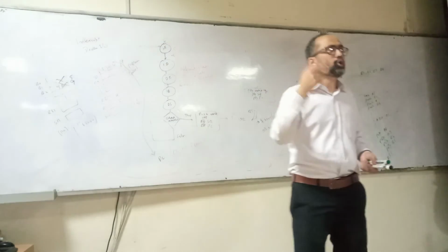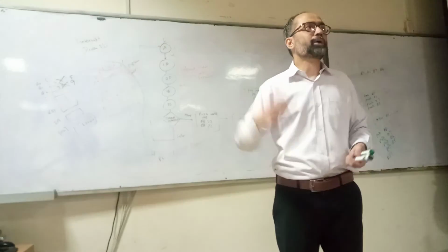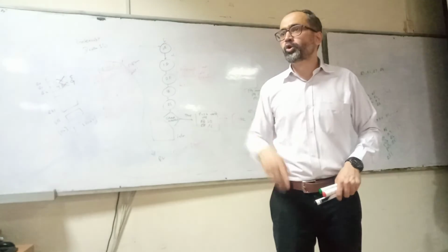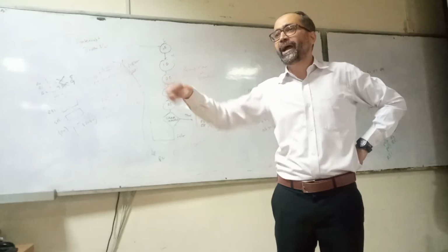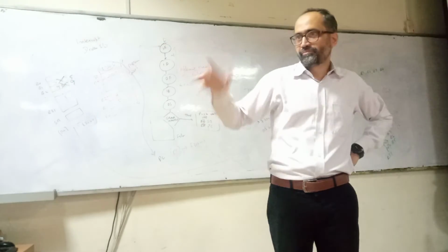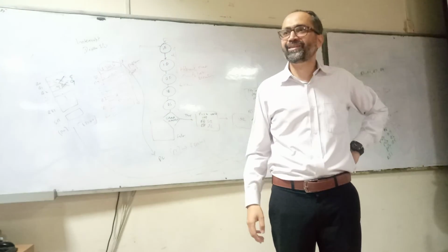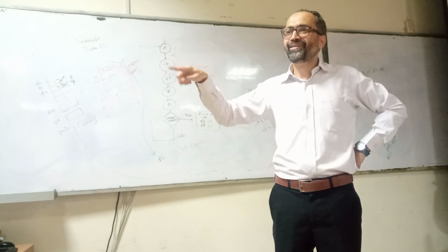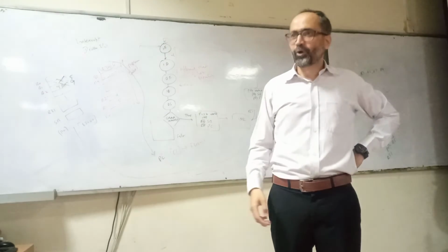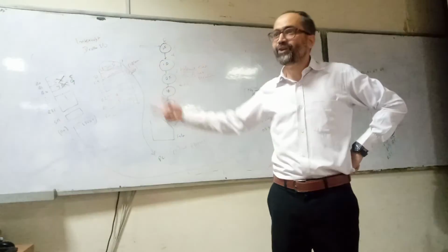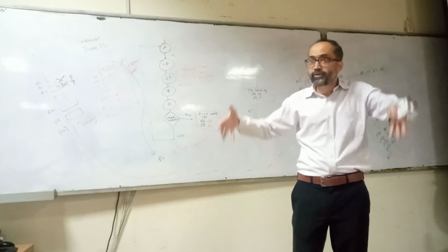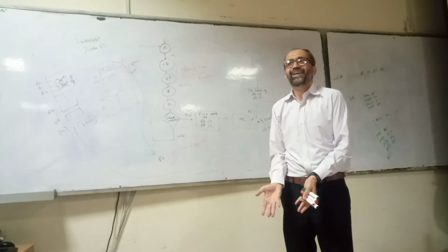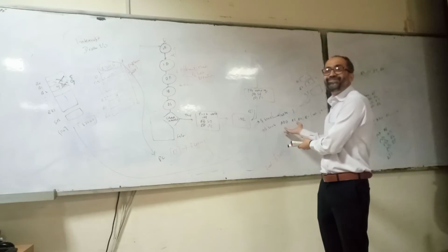First you have to define a loop counter. Let's assume the loop counter is R10. So you initialize this value, move R10 #100. Now you initialize the loop counter. Okay, then you decrement the loop counter, decrement R10. Okay, then you compare R10 with some value. So if you look at the loop, these are all instructions. And an instruction can be of any type.